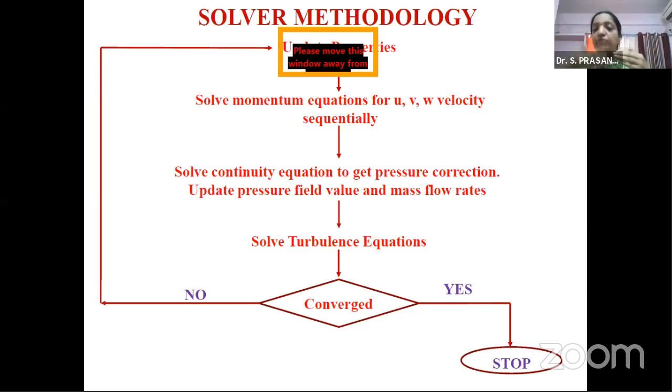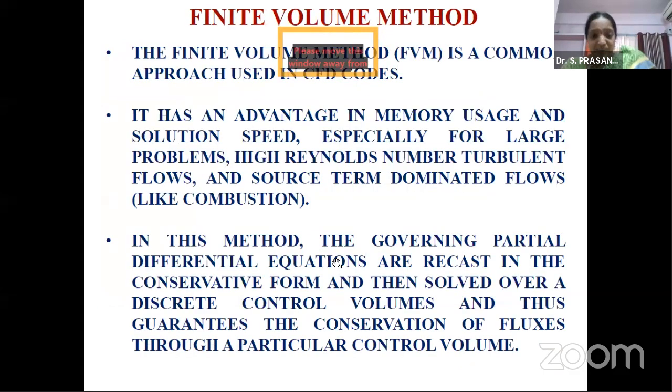So this is the solver methodology, which is called the pressure correction method. And the solver using this pressure correction method is SIMPLE, the Semi-Implicit Method for Pressure-Linked Equations. So once this is done, as I told you, this is the process that takes place.